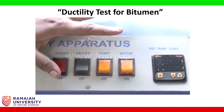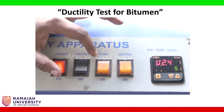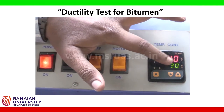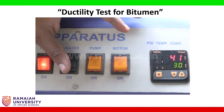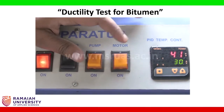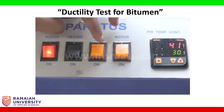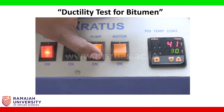When we switch on the equipment, it asks for the standard temperature to conduct the experiment. If you observe, the standard temperature required is 30 degrees. If it is in a cooler condition, we are going to switch on the heater and raise the temperature of the water. And if you want to remove the water present in the ductility apparatus and put in fresh water, you use the pump.